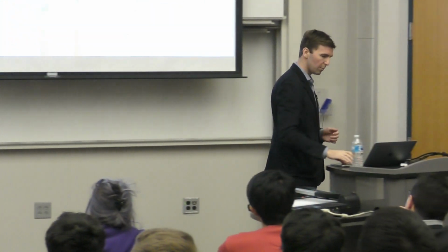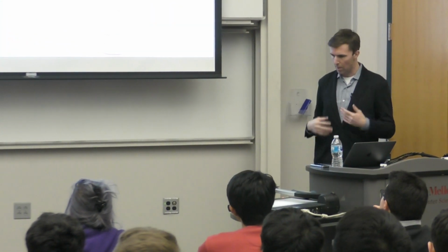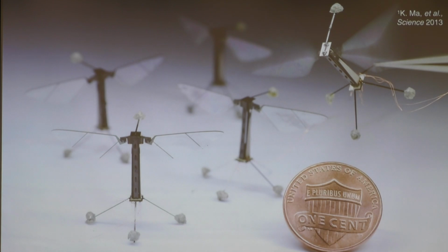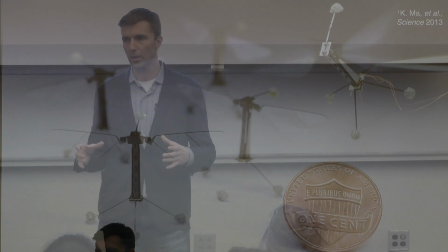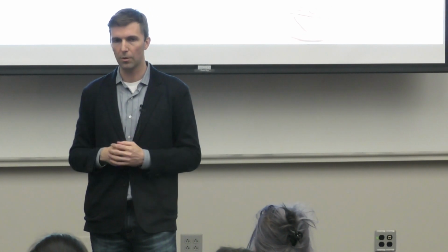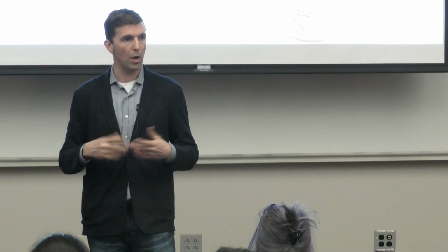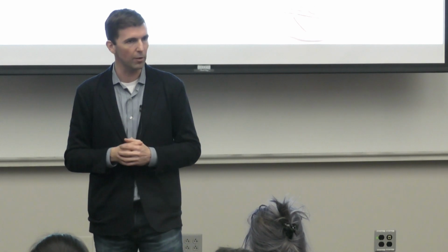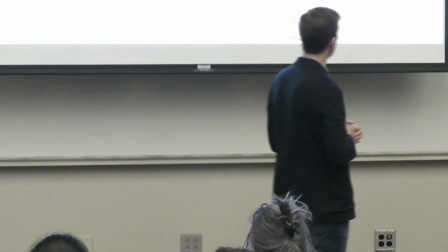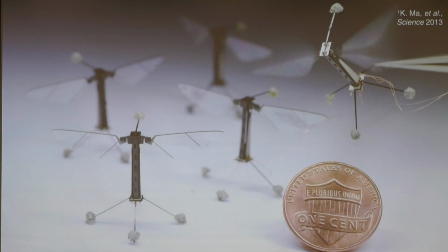Okay, so this has a number of nice features that I'm not going to really dwell on. A couple things I will mention is that we can make any mechanism or any structure, and again, we can use any material. The other nice thing is, like I said, we basically made a multi-layer printed circuit board, so we can fabricate circuit elements directly onto these two-dimensional composites prior to folding, and then pop up and you have monolithic electromechanical devices. We can embed actuation that way. We can embed sensing that way. We can embed computation or power that way as well.